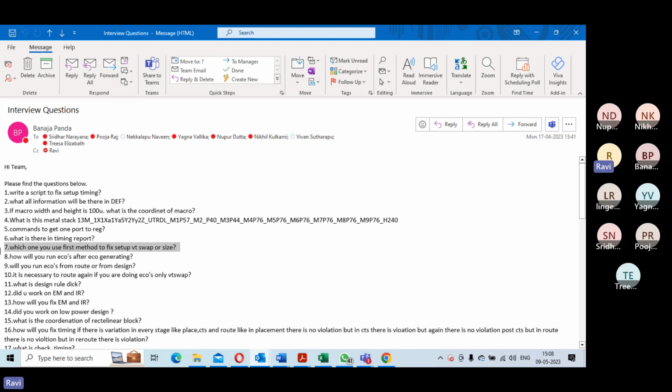Functional ECO, when you are getting it, you will freeze the database before you implement the functional stuff. Then you will dump the netlist, and then read the functional ECO into your design, take the diff and implement that. Then dump the final netlist and do a formal verification, an LEC check, between the final netlist which has come and the ECO-implemented netlist in your database. Both should be the same.